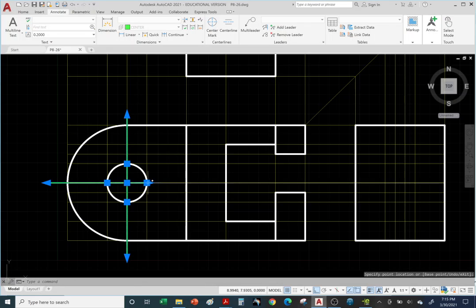All right, and let's extend. Oh, went too far, way too far. Let me turn off object snap so I can have control over that extension line. Okay, hit escape. Now in this case, we're not going to overextend the green center line because the top is not symmetrical to the bottom. As you can see, it's not symmetrical. So we'll leave it the way it is.